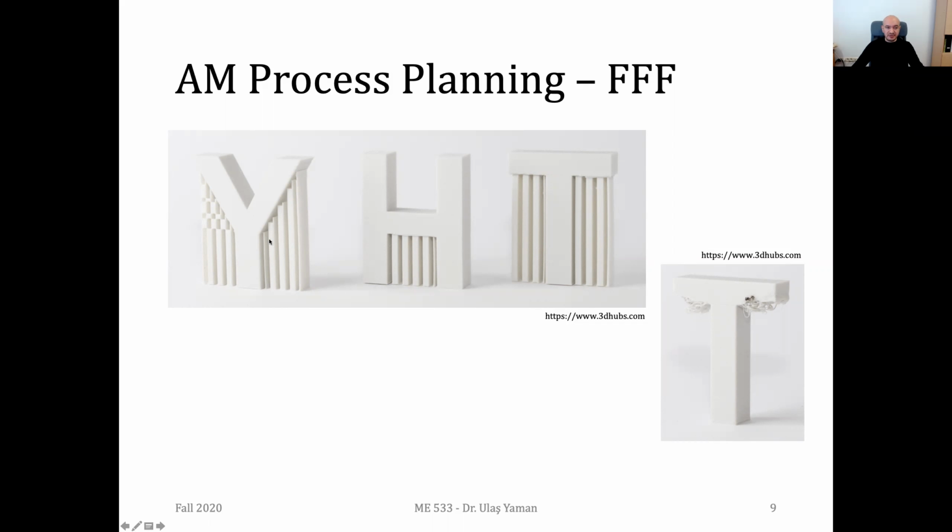And we also need to use support structure for some inclined planes. I usually prefer to use support structure for the angles which are less than 45, depending on the reference plane. So if you have higher than 45, you don't need to use it, but this is also another parameter which can be set in the CAM software.